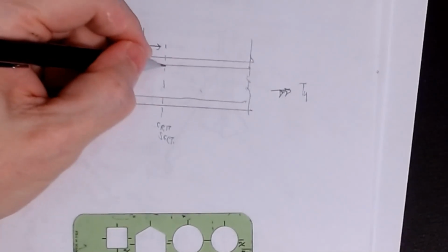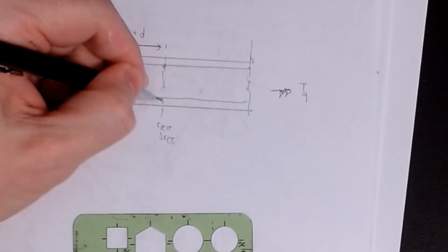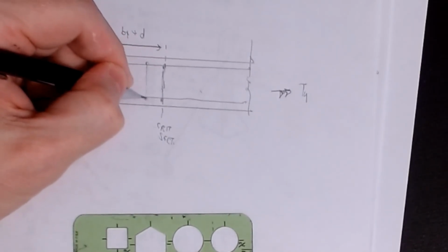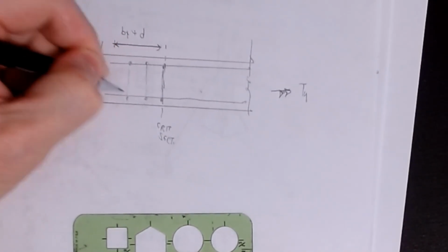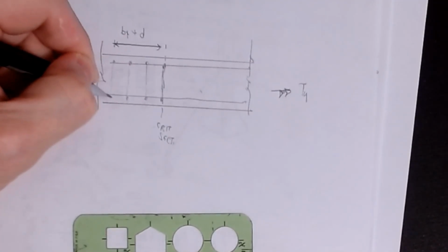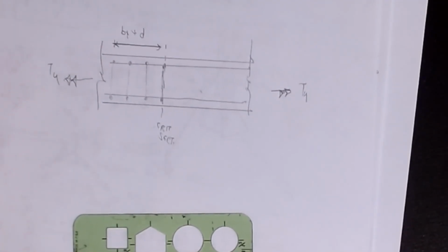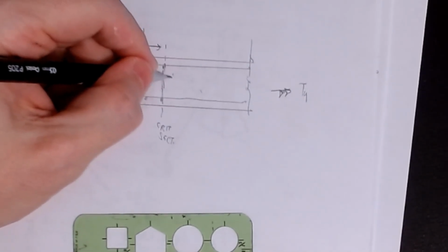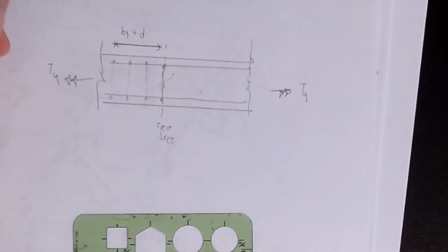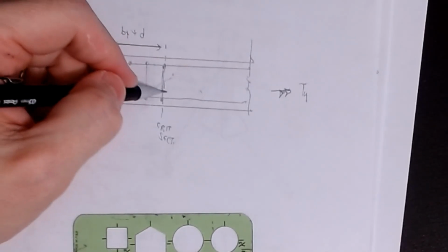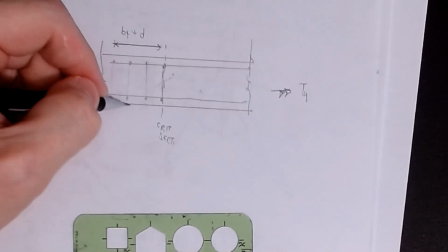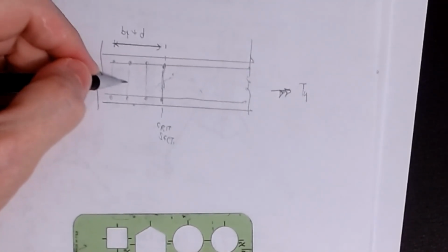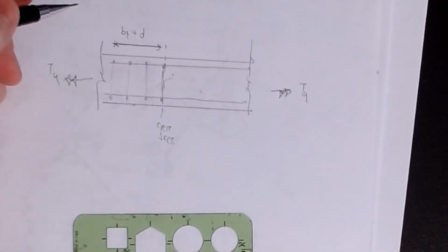So now I've got, so say I put one here. This is the one that I'm doing for my critical section. Okay, I have to continue on with the same spacing for a minimum of that amount of distance. Okay, and the reason for that, again, is because of this helical crack. If I develop a crack here, on this one at that critical location, this bar captures this one, but as this crack propagates down and then we go across the bottom, now it's this bar over here that's arresting that same crack. Does that kind of make sense?